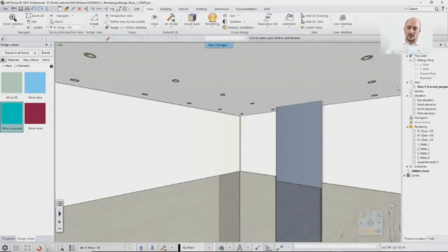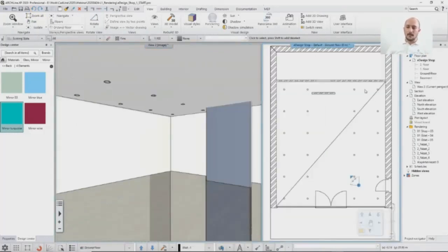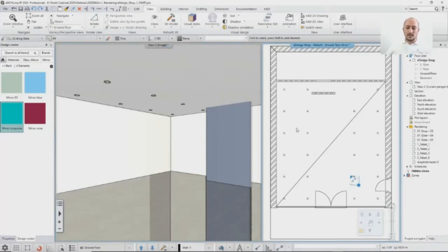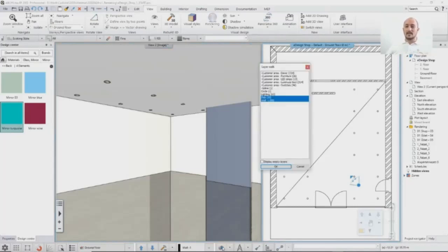So how to do that? You need to go back to the 2D, and you don't even have to switch drawings. It's just important to make it active, and then you can go into the layer settings. And why is it important to switch back to 2D? Because if you are still in the 3D and you click here, you will see only 3 layers, because in the model you only have 3 layers, since you didn't build the content of the rest of the layers. If you go back to the 2D, you will always see all your layers, and based on those layers you can build what you would like to see in the 3D, and only those layers will be available in the 3D. So that's important.